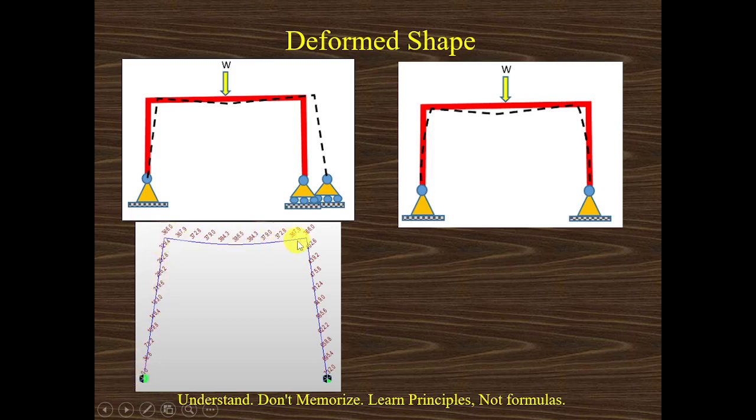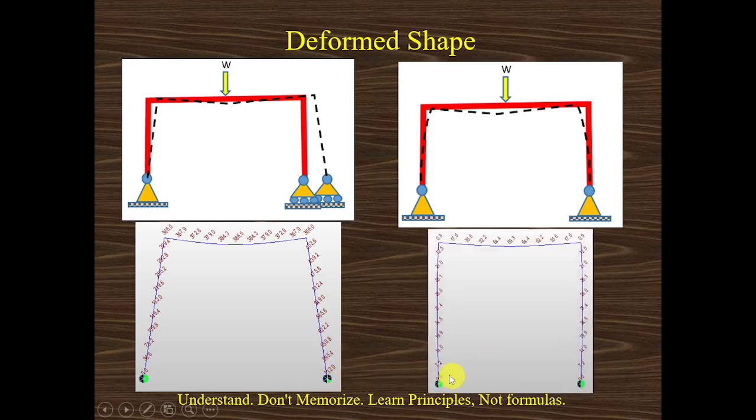Whatever values we are seeing are the translational deformation in mm. The vertical beam also gets deflected almost 386.5 mm, and the right support moves almost 732 mm for the 1000 kN load. The length considered in this exercise is 5 meters for each element. In the case of a pinned support at both ends, this 732 mm deformation is arrested, so the diagram is going to be similar to this, with 0, 0, and the deformation is going to be some number.